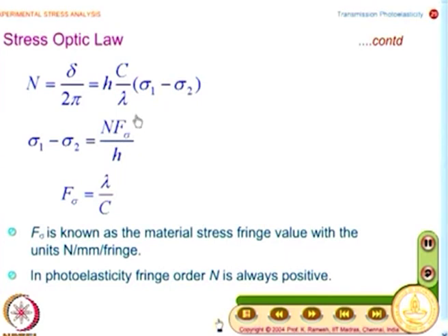So, what we will do is, we will have a detailed discussion on how to find out f sigma as accurately as possible. And from the photoelastic point of view, we will have to find out how to get the fringe order n. I cautioned you even several classes back that in all optical techniques, finding out the fringe order is tricky. You do not get it in the first go. You have to use auxiliary methods, you will have to develop engineering acumen, you have to verify from various methods of finding out, and then another question is, you find only the fringe orders at the fringes, you do not find them in between fringes. So, you have to use compensation techniques. So, finding out fringe order is an issue.